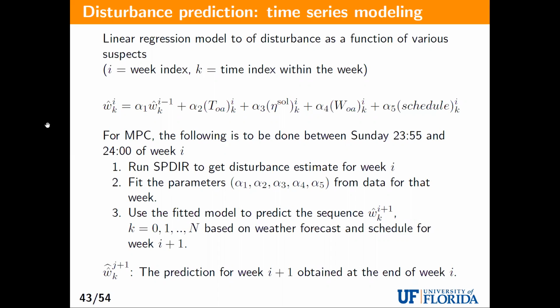So this is a completely time series model, because this is supposed to tell us what the occupants are going to do, and there are no Newton's laws for occupant movement, right? So this is not a physics-based model. The only thing I'm doing is using knowledge of these previous signals. There is no heat balance equation or anything like that here. I'm just using previous samples to fit this model, and whatever I get, I get. So that's the problem with this, but that's what we've got.